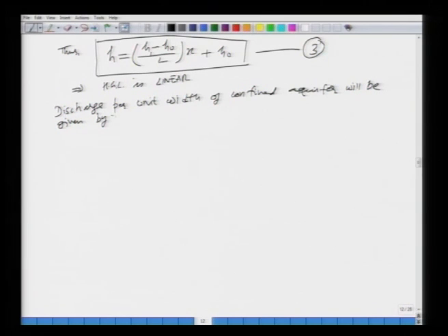We can use Darcy's law. This is going to be equal to minus k dH/dx. V is equal to k I, but if this is the discharge, I can multiply this by B, and this is multiplied by 1 unit width. So, you are multiplying by the area. This is basically your discharge intensity.